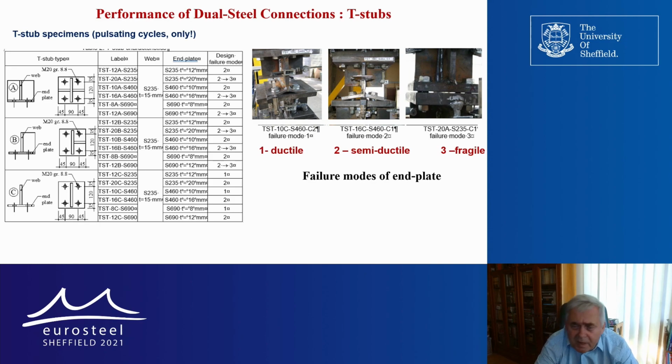The fragile mode is good because you can always obtain full strength connections. But anyway, this fragile failure in case of an extreme earthquake could be dangerous to accept. That's why the attention was mainly focused on the semi-ductile mode.